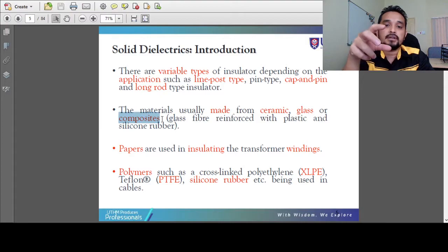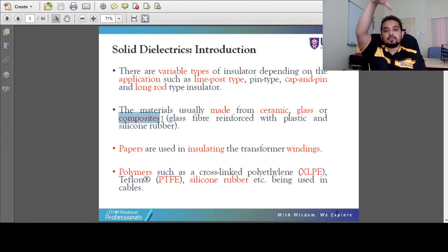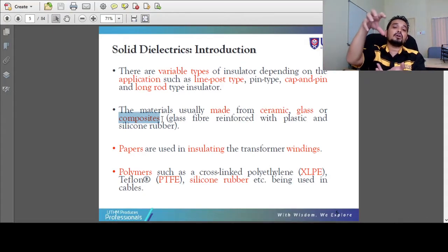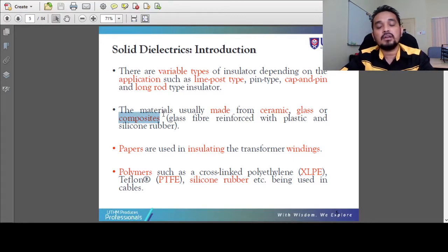Another thing, if you suspend about 10 or maybe 20 ceramic and glass discs altogether, they can only be lifted by a crane. Just imagine how we are going to install ceramic and glass insulators along Peninsula Malaysia, on the mountains, and how a crane can get access to this kind of area.